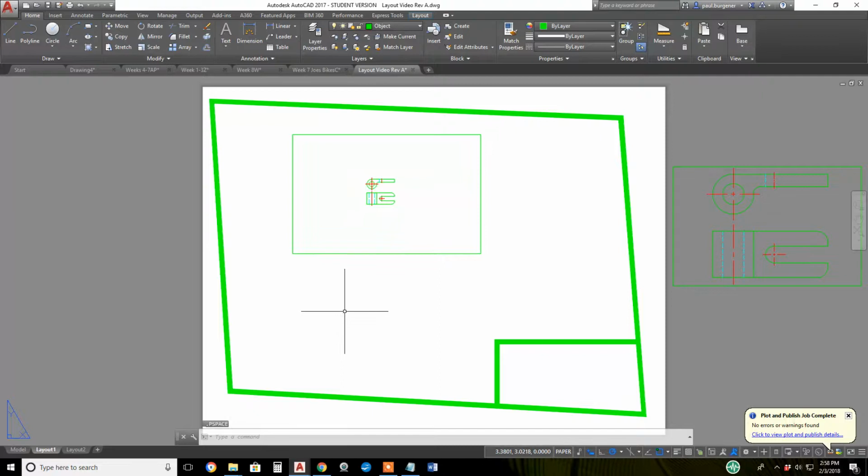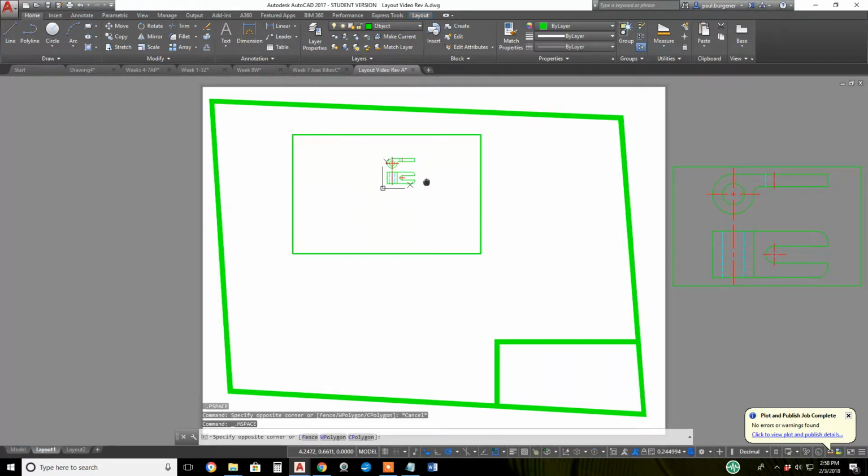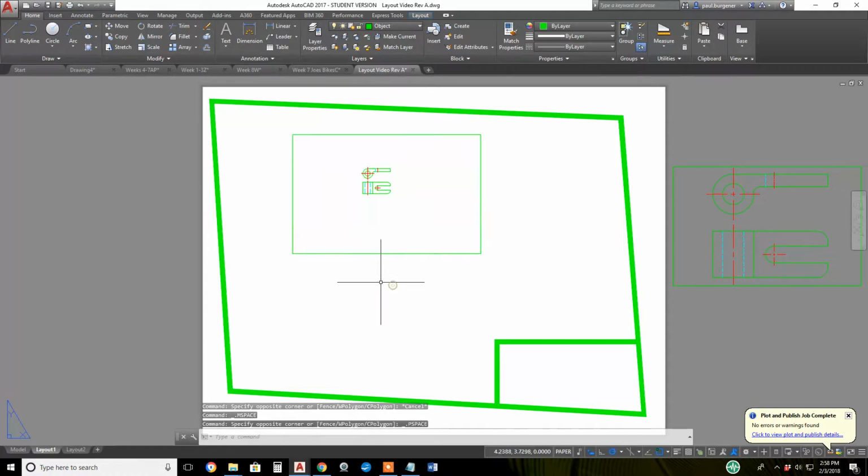Double click outside, you get back the blue triangular cursor or icon in the lower left corner of your screen. The viewport becomes faint, the model space logo disappears, and the word paper appears on the status bar. So you got 3 or 4 visual indications whether your hands are inside the glass working in temporary model space or your hands are outside the viewport working in paper space.